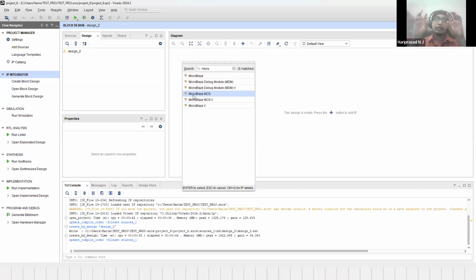Whereas if I try to implement RTL for all these five interfaces, it is going to consume that many LUTs and resources, and that much time for development of these IPs and for interfacing and integration. So there is always a thin line in deciding whether I put a particular application on the software side or on the hardware. In any FPGA system you consider, there will be some part which we have to put into software.